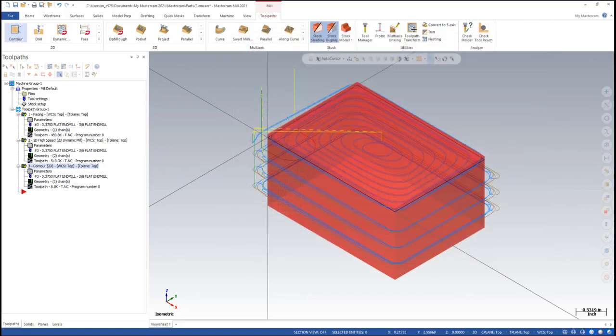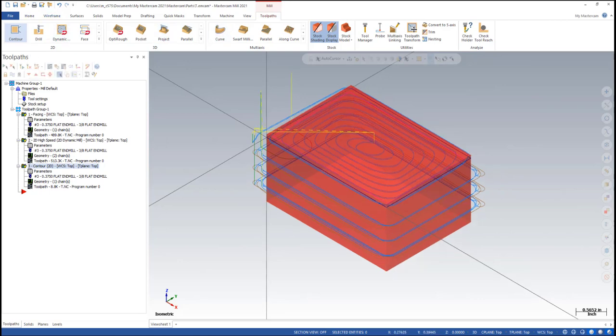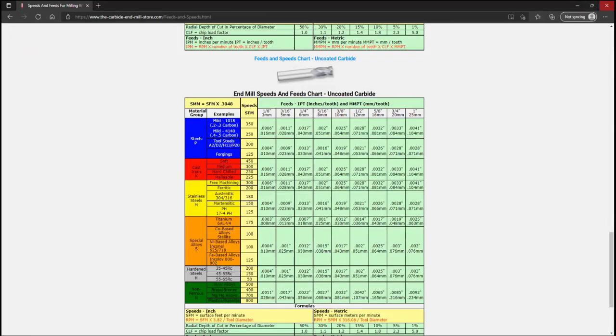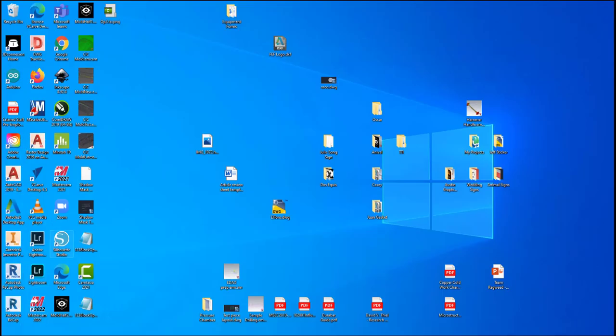We can go ahead and close Code Expert. And if we wanted to, save our Mastercam file. You're going to want to save often. Sometimes Mastercam has been known to crash, so be sure you save your file as you go, any chance you remember. And if you go to your desktop, you can find the program that you wrote.